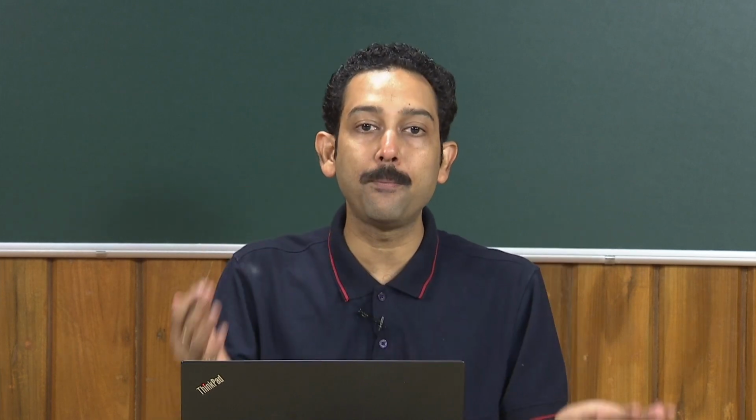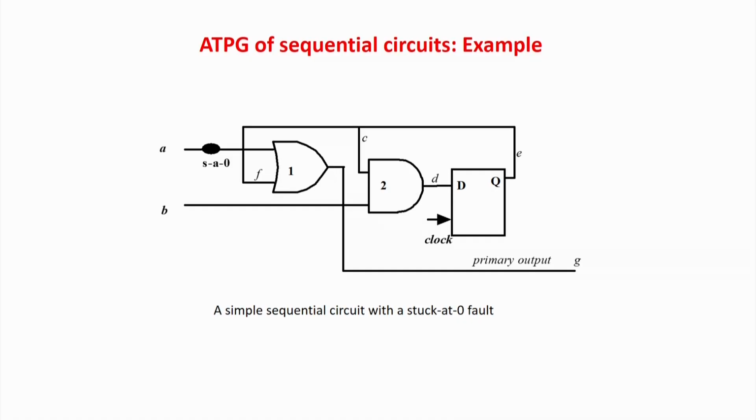Now, we will see the challenges of structural testing for a sequential circuit. We will appreciate that whenever we go to a sequential circuit, the complexity blows up and it becomes a more difficult problem to solve. In the last class, we took different circuits and saw that there are two ways of test. One is called the random pattern test, and the other is the sensitize, propagate and justify kind of test, where difficult faults are tested. For sequential circuits, we will mainly focus on the sensitize, propagate and justify approach, because the complexity starts with such difficult-to-test faults.